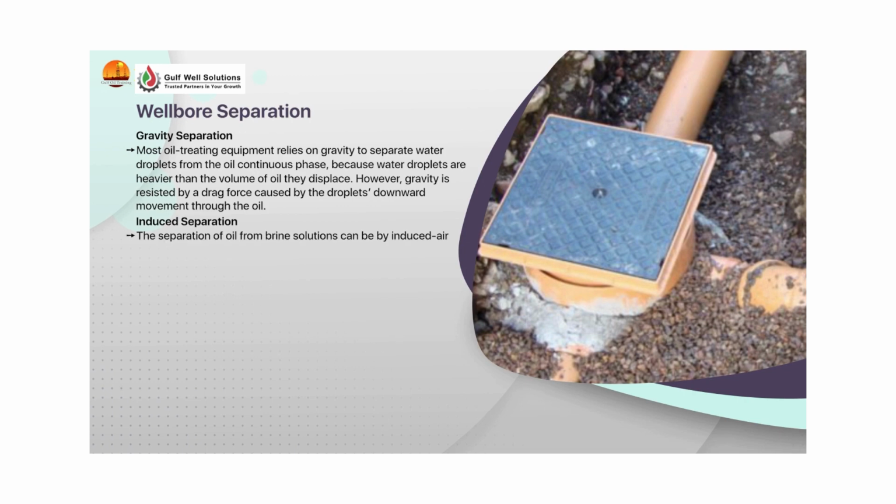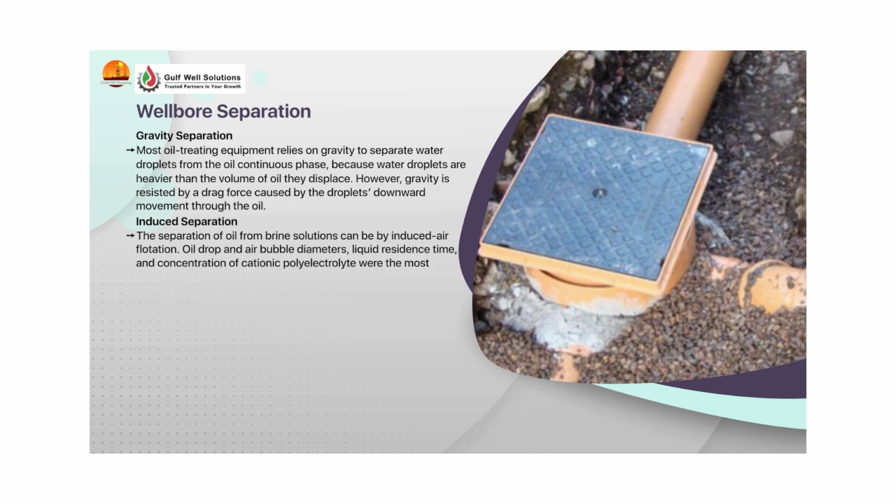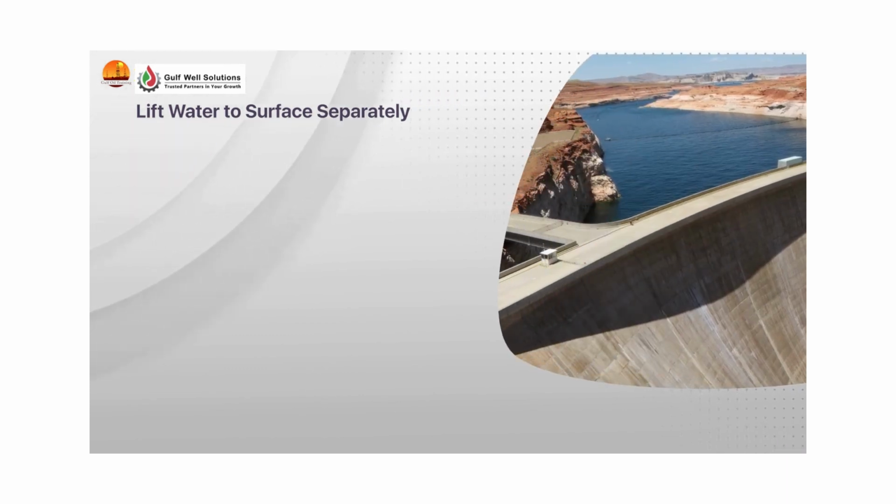Induced separation. The separation of oil from brine solutions can be by induced air flotation. Oil drop and air bubble diameters, liquid residence time, and concentration of cationic polyelectrolyte were the most significant variables affecting overall flotation performance. Lift water to surface separately.